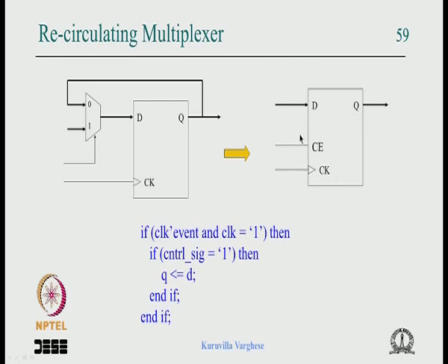One level of 2-to-1 mux is available, but if you need further control, then you need to have the muxes outside. This wouldn't help you, but in most cases, on average, you need one level of control, enabling a counter or enabling a register and so on.